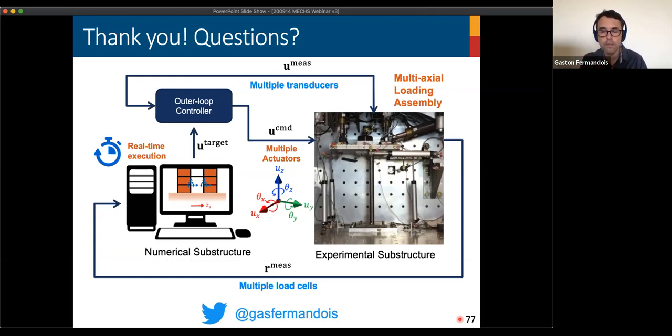In MBC, the model-based compensator, we use an LQG with LTR, and it was tuned so that the shaping of the open loop transfer function has some properties that we deem appropriate in order to run the test. Meanwhile, in the decentralized version of the problem, we use this modified MBC, where we installed a